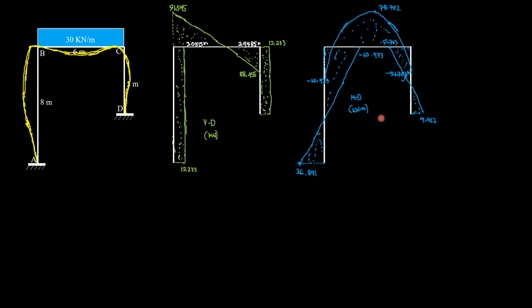Finally, for the elastic curve, we have positive moment here, then negative moment. So concave up, if this is the upper fiber, concave up curve. Then for this portion, concave down. Remember that we are viewing in that direction. This is the upper fiber. So concave up, concave down.